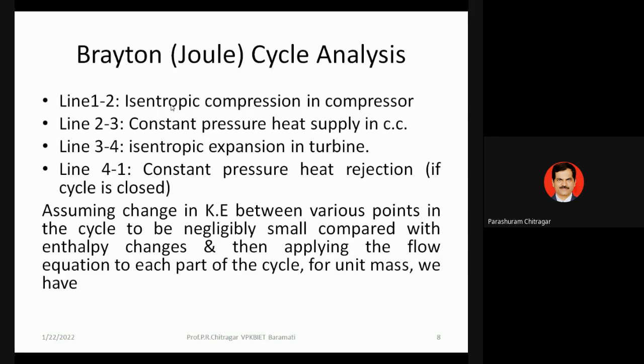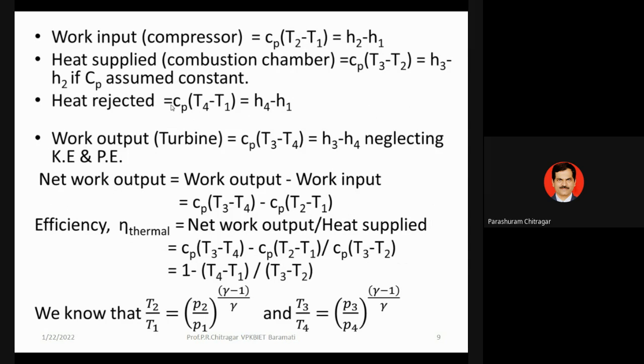Okay, so for the rest of the changes, whatever kinetic energy and potential energy parts there are, we neglect them. Okay, we consider this as small. And then we will apply this SFEE, that is the steady flow energy equation. Every analysis used in a thermodynamic cycle or in mechanical engineering will be based on 1 kg mass, okay, for unit mass. Then if we calculate it in terms of specific heat and temperature, okay, first let me show that diagram and then we will come to this part.